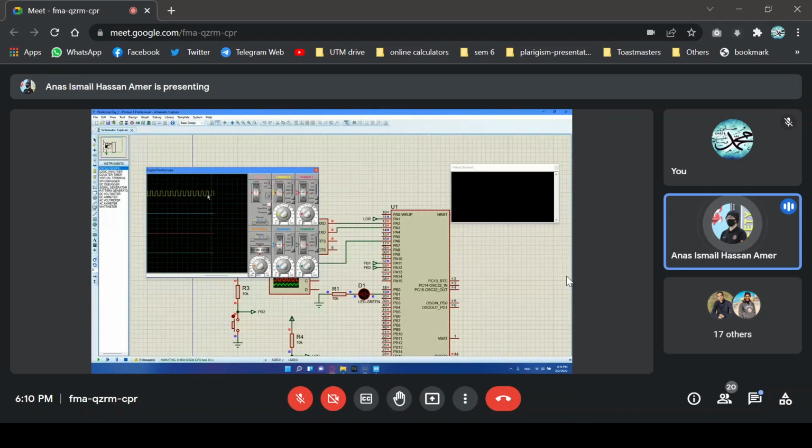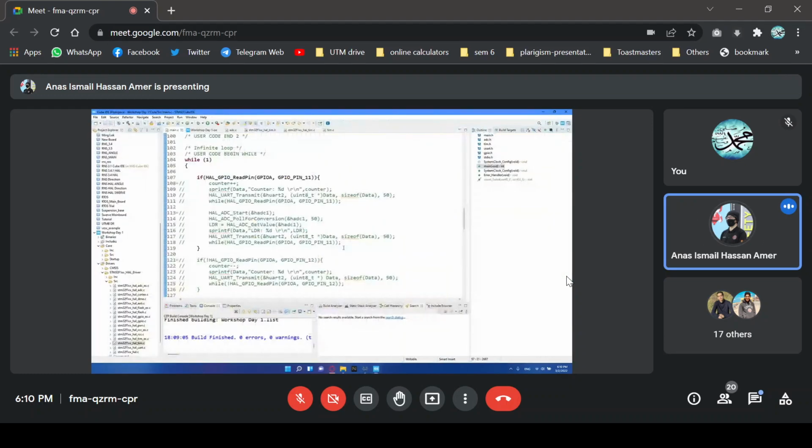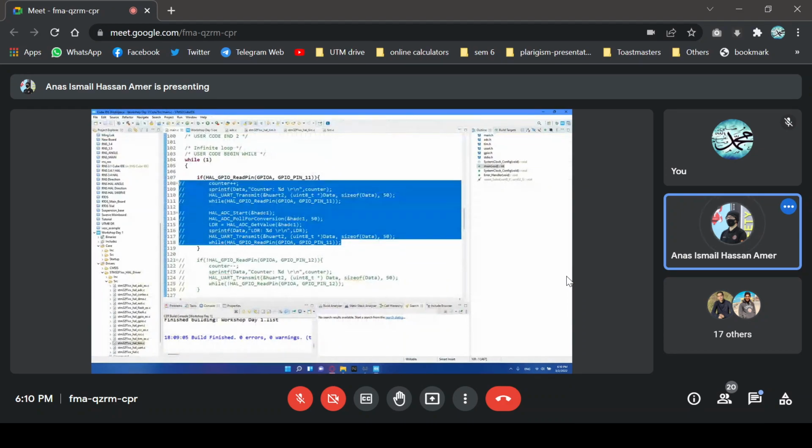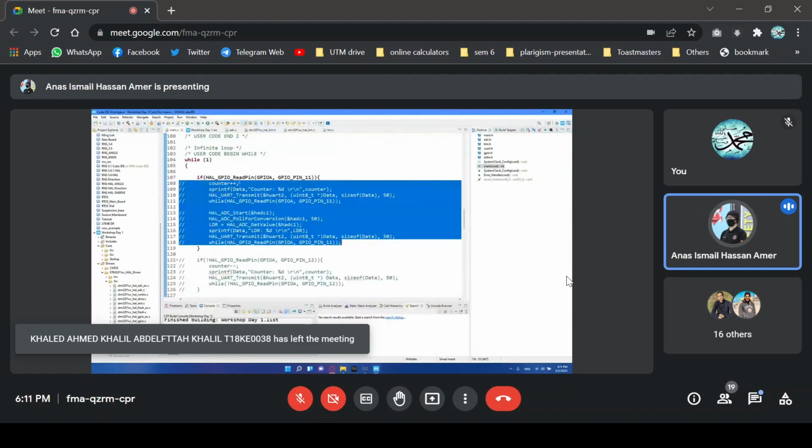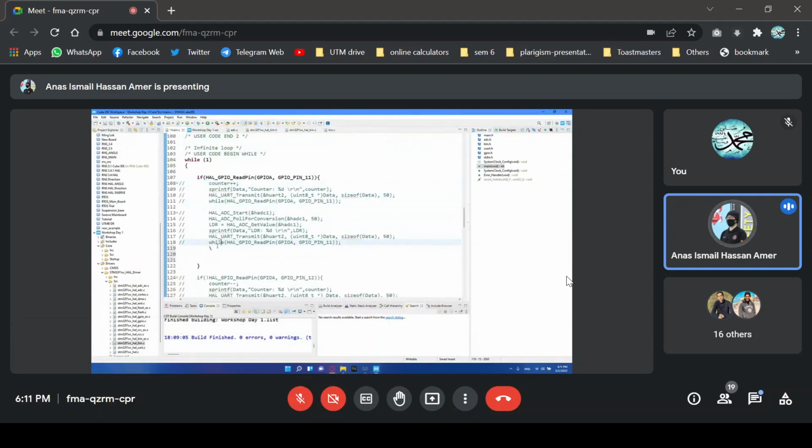So let's try to play with the PWM that we are generating. Let's try to change the pulse when we press the buttons. In order to change the pulse, you can directly change the register, or you can use a definition that they have defined already, or you can deinitialize and then reinitialize with a different pulse, but that's too long. So let's use the function that they have defined.